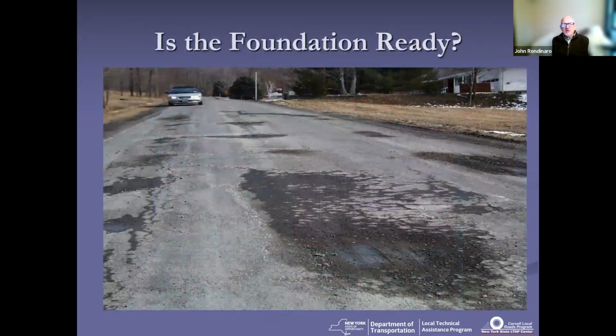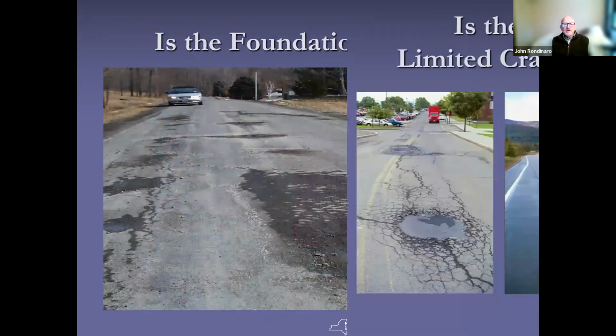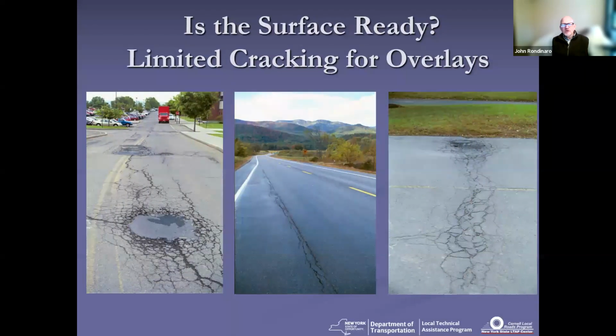And one of the starting points that Gary worked with was, is the foundation ready? And if your pavement looks like this, I'd say your foundation is not good to go yet. First thing you want to be looking at regarding the surface is any cracking. You want limited cracking for your overlays. So if you're looking at that left-hand slide, that pavement is too far gone for an overlay. You're really going to need to look at a more extensive treatment.